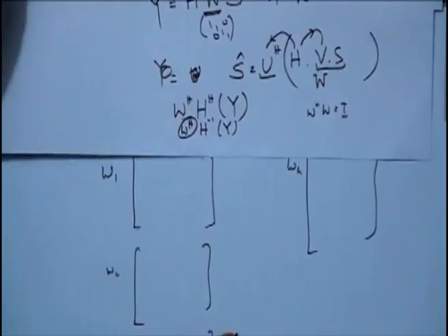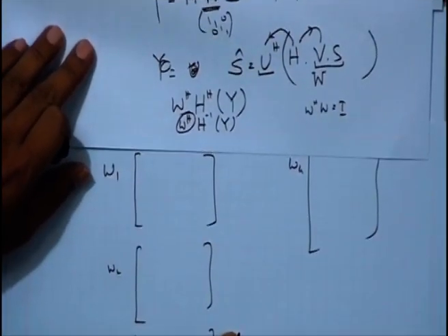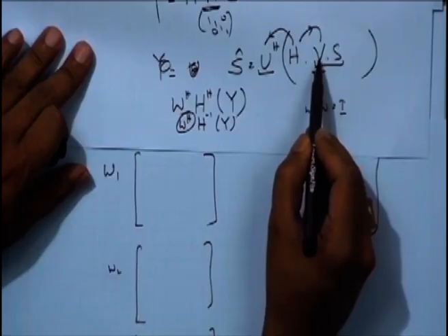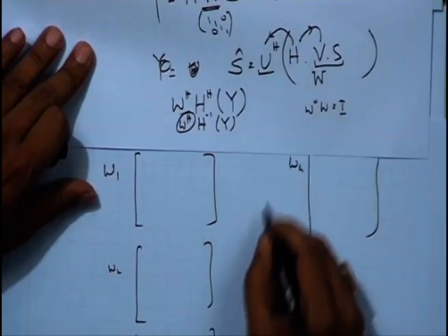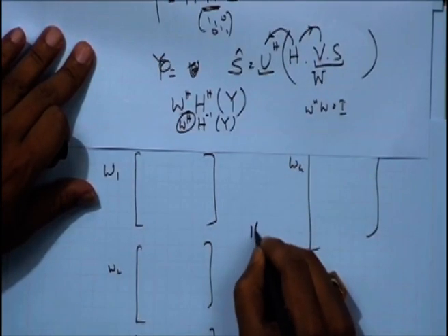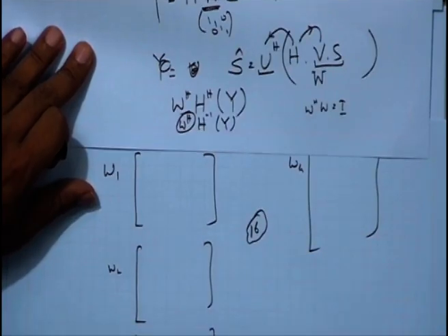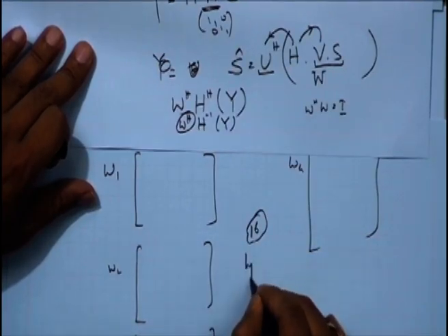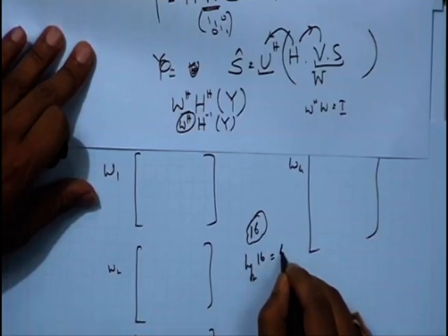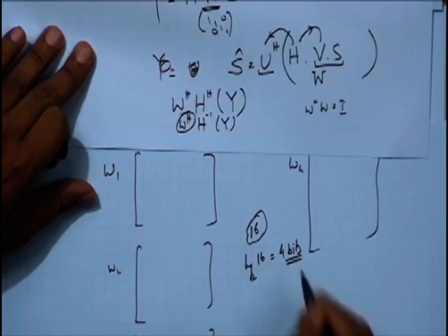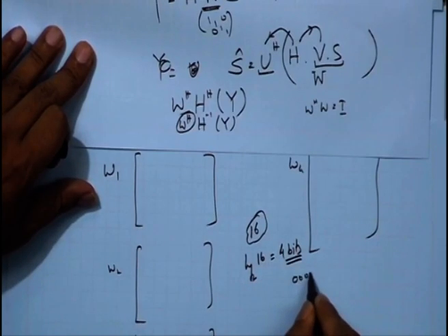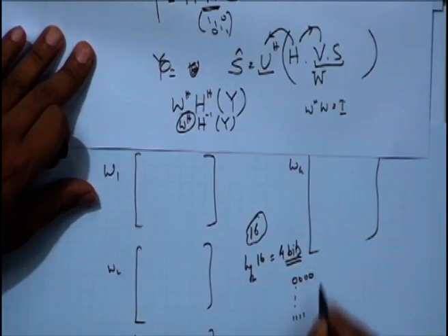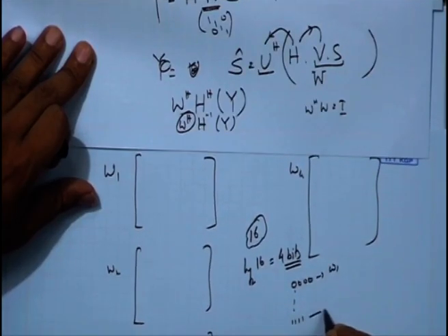So, this hints that if we are choosing predefined matrices, the gain that we get is we do not have to calculate V, we do not have to send back V. So, if we have, let us say, 16 different choices of W, all we need is log2 of 16, that means 4 bits of information, to select from 0000 up to 1111 to indicate different W's.